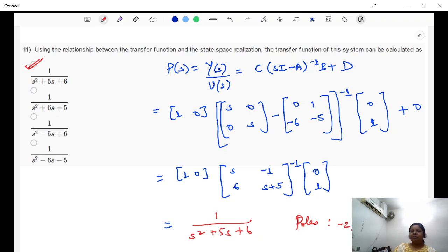For example, you have the state space equation over here, and you are supposed to find out the rise time or maximum peak overshoot. What would you do? You would go from this A, B, C, D state space representation to the Laplace domain, because zeta and omega n are defined that way only for a second order system. You would go to the Laplace domain, compare omega and zeta, and then find out, okay, this is my peak overshoot. So that is one of the ways.